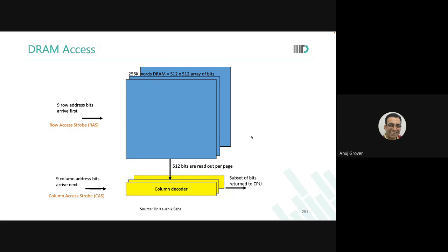Are you able to see this? There is one more thing. The sense amplifier decouples the bit line, so that is where you can pipeline it. The next stage can start the row decoding.